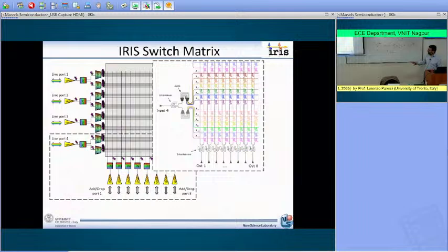Then after the interleaver, we have a demultiplexer stage, meaning a stage which is able to route all the different wavelengths, so the 12 wavelengths, into the different waveguides, which are the different rows of our switching matrix. This is the demultiplexer. And by using this demultiplexer, now lambda 1 is going in this row, lambda 3 is going in that row, and so on and so forth. And so we have demultiplexed the input wavelengths along the different rows of our matrix.